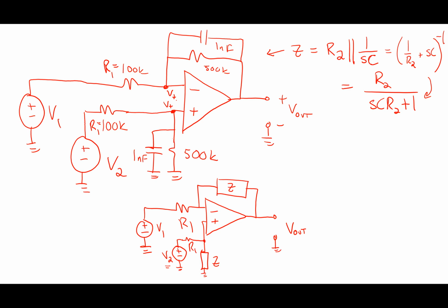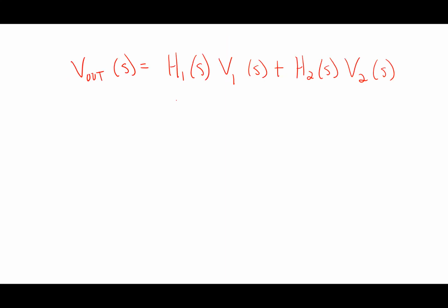But if you think about it, superposition is a mathematical trick. When I work a circuit, I don't turn V1 and V2 on and off independently to analyze it. They both work together. In superposition, what do you do with a voltage source? You turn it off, setting it equal to 0. So if I turn off V2, what happens to this term?